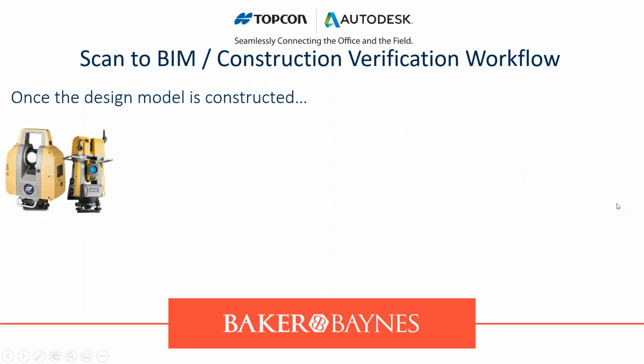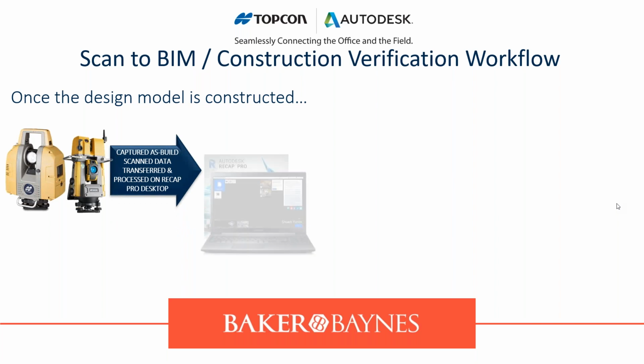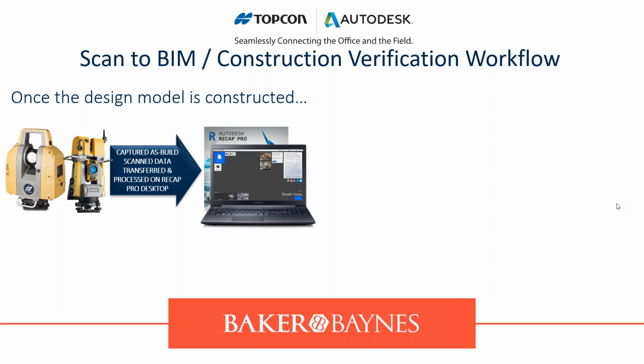You will go and do a scan with a laser scanning technology, right? So you'll use, in this case, I'm advocating Topcon. So you'll use the GLS 2000 or the GTL 1000, whichever you want to use. This will actually capture the as-built data or the scan data and transfer it to be processed on Autodesk Recap. Okay, so this is on your desktop. The cool thing with the Topcon is you have an SD card which you can plug directly into your laptop, and you can actually process it, which makes it very simple, right?